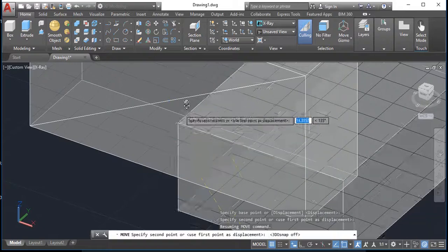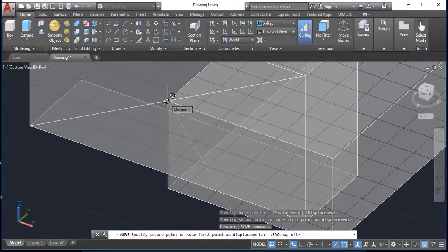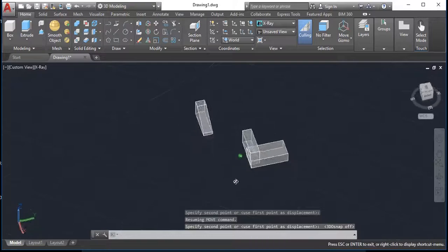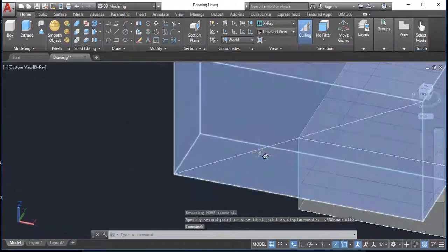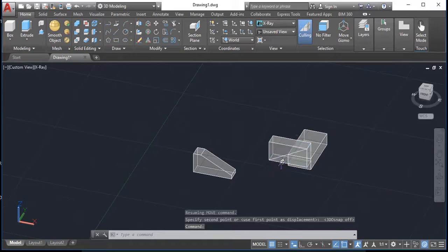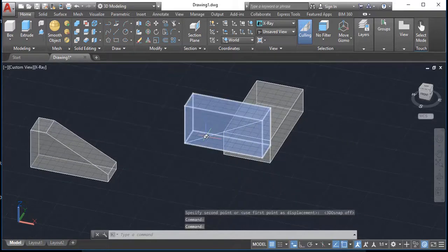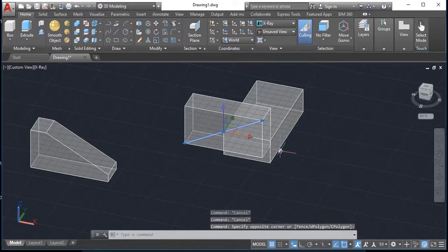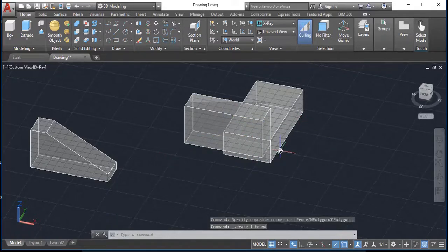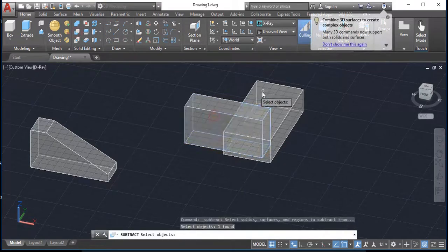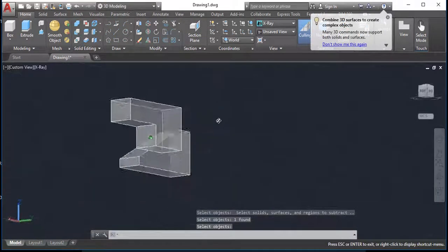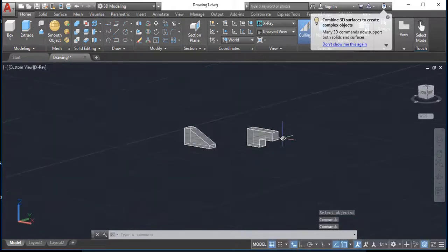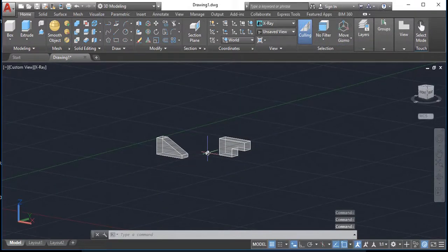Let me turn off F4, which is the 3D snap. I could snap to a point on a regular line. So I've now moved that box from that corner to that line point. If you do that, just please know that you need to go back and erase your actual line itself. You can do that by just windowing a solid window and hitting delete to erase that out. But you can use line points to locate your boxes or your different shapes in AutoCAD. You can use lines to locate those points. Okay. Any questions on that stuff?